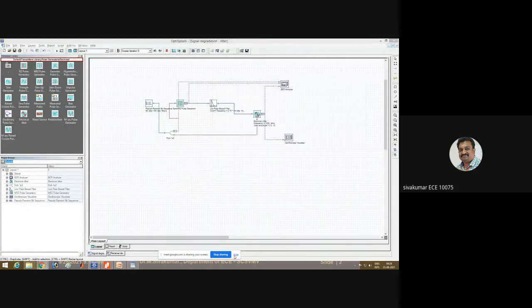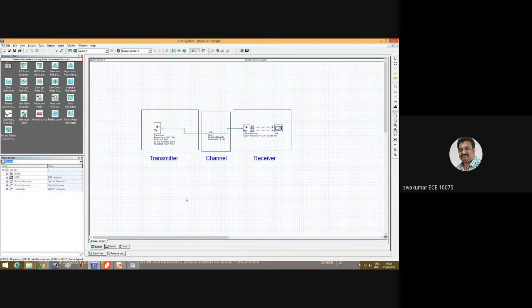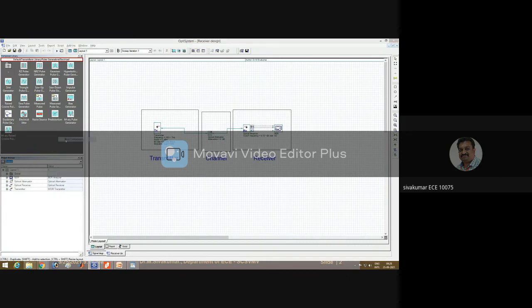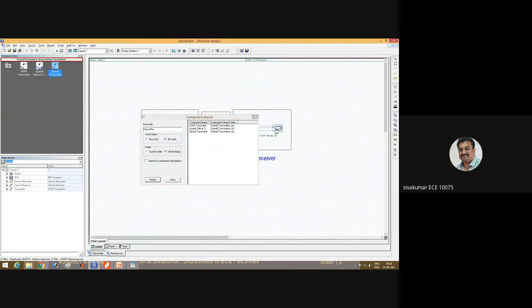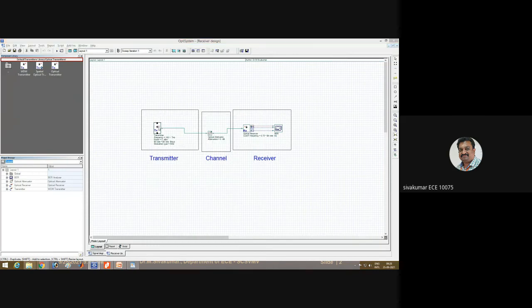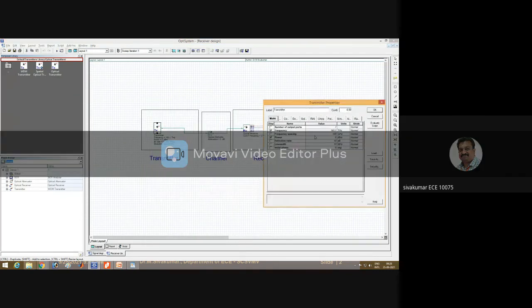And the next one, basic optical transmitter, channel and receiver. For this transmitter, just find the component, type transmitter. Here, choose optical transmitter, and just drag and drop the optical transmitter and receiver as they are, and the optical attenuator. Here, you set the frequency in terahertz, meaning 193.1. We choose the unit nanometer, meaning you select 1550.